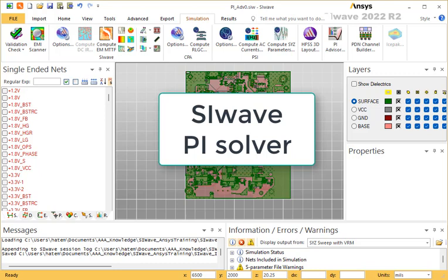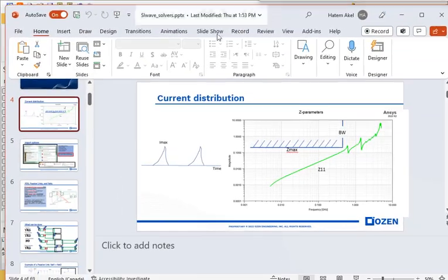Drivers, power amplifiers, TIAs, and many chips withdraw constant current. But most ASIC chips withdraw variable current. That means the current contains a DC value and a spectrum of frequencies. Consequently, we need to understand the response of the power planes along this spectrum.